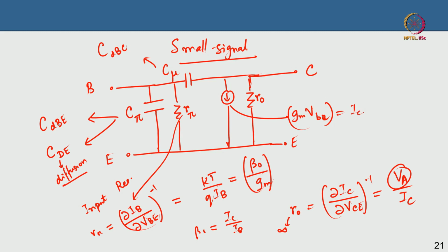Just remember that whenever I am using capital VCE, it means the DC bias I am applying, and a small symbol here, for instance vbe, it means the small signal that I am riding between the base and the emitter, the small signal base emitter voltage. Just to keep the demarcation clear, anything that is small, for instance ib is the small signal base current, ic is the small signal collector current. So that is the nomenclature we are using here.